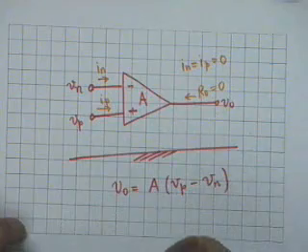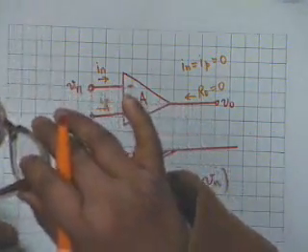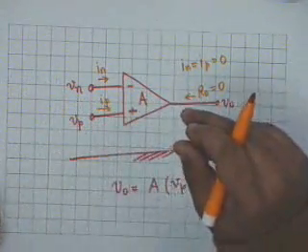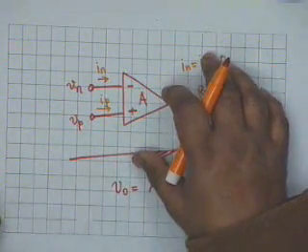What is your source of energy? These two batteries. Now, you know that batteries have a limitation. They cannot supply more than a certain value of current, and therefore ideal is ideal, but for the limited purposes of instrumentation and control, the ideal characteristics are almost always valid, and therefore we usually treat an op-amp chip as ideal, unless it is a critical application where we shall have to look into the sources of non-idealness. Let me quickly give you certain practical applications of an op-amp to give you a feel of what an op-amp can do and what an op-amp cannot do.